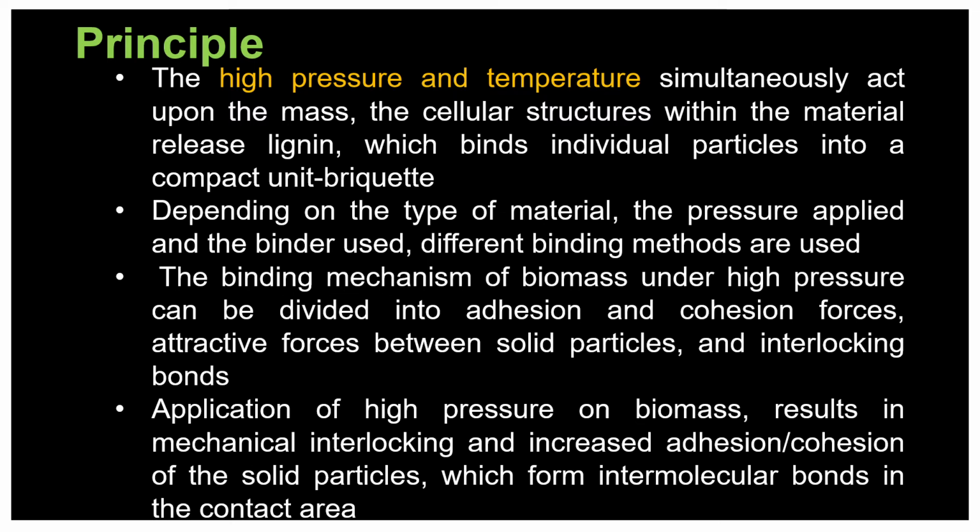So lignin will squeeze out of the material, and that lignin will act as a binding agent to hold these materials together as a single unit, like a gum, providing adhesion, and hence the material will bind together as a single unit. Depending upon the type of material, the pressure applied, and the type of binder material used. If the lignin content is not naturally present in the material, we can add an extra binder material for proper binding. So all those things are there.